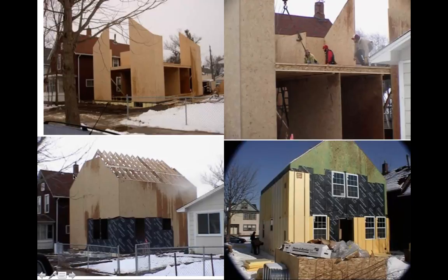So you have the loads coming down here from the roof and from the snow load that's going to be supported by the column over this whole length. Well, if you think about a fairly narrow column over this whole length, that's going to be much more difficult, and it's going to be a much too long a buckling distance. So in building this, you actually use your second floor, or the I-beam to support the second floor, as a bracing system.